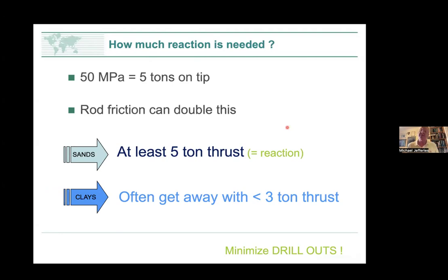And that's very convenient for tailings, because if you keep in mind, perhaps the reason you're listening to this talk, you're more interested in liquefaction. Well, liquefaction is associated with softer and looser soils, and they, in particular silts, if we're in the tailings business, are much easier to get a cone into the ground.